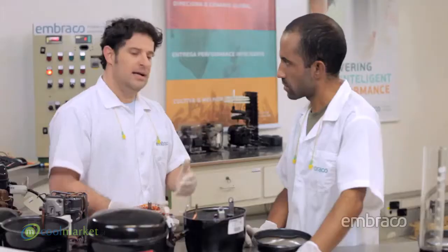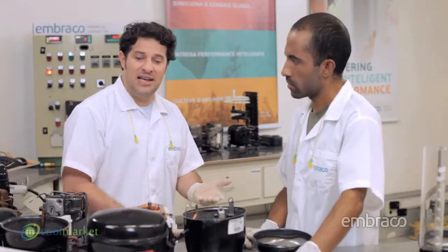Incidentally, when the compressors are forwarded to Embraco for defect analysis, it's essential that they be properly handled and stored. They can't be thrown, turned over, or shaken, as well as also be sent together with the electric kit used and its tubing plug to prevent contamination.